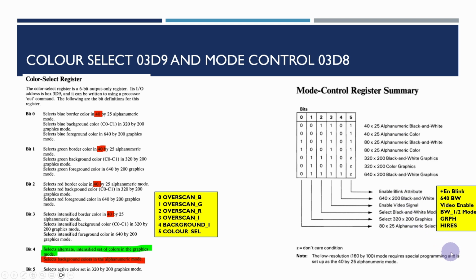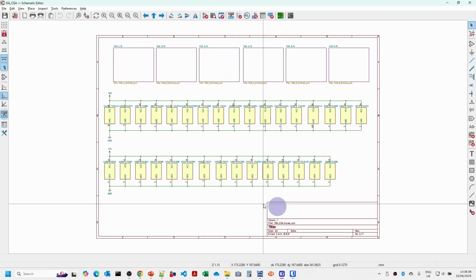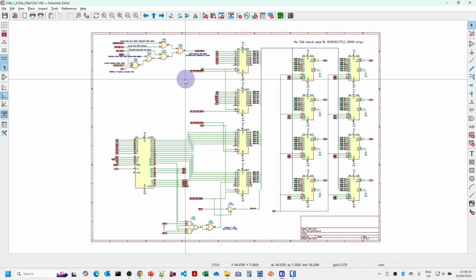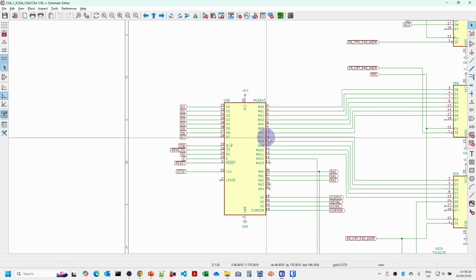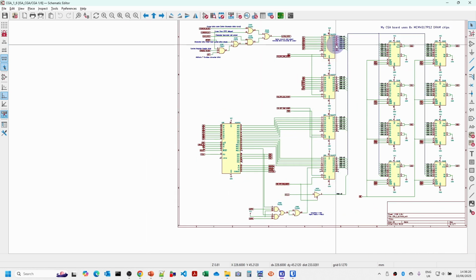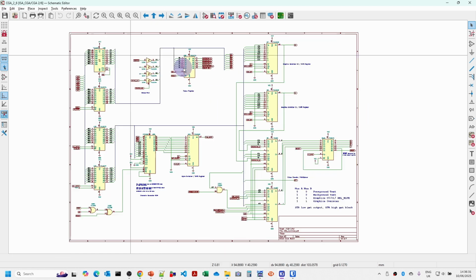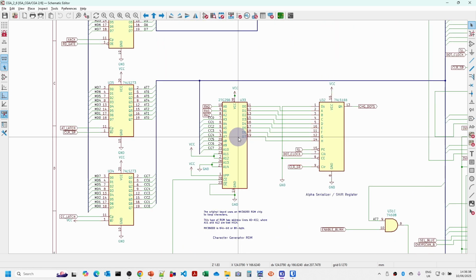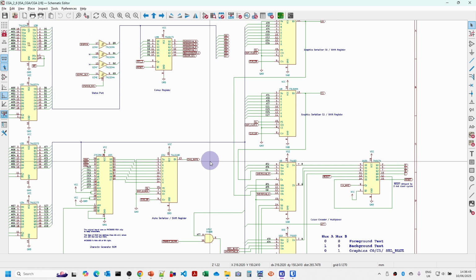So now I'm going to go through some of the schematics from the original CGA card. This is a project which I've referenced previously, and this has KiCad versions of schematics that have been converted into KiCad. So this shows the CRT-C controller, the video RAM, and the address latches and buffers. Then we've got the various attribute and character latches, the video ROM and the shift register that's producing the dot output that we covered in the previous one.